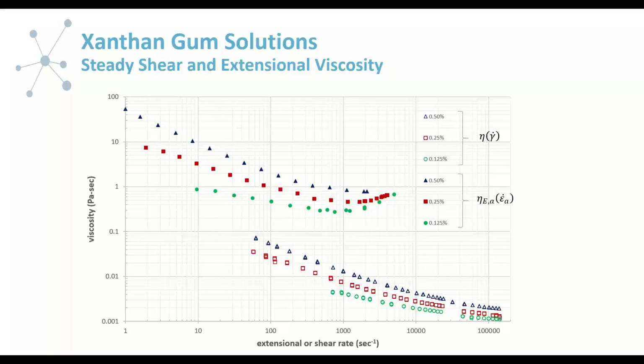And this is true even for Newtonian fluids, but it can be exaggerated for complex fluids, such as this high molecular weight polymer solution. The other thing to notice is that although we see thinning, or reduction in the viscosity as a function of rate, in the extensional case what looks like it might be extensional thickening, or an increase in the extensional viscosity, is absent down here under the steady shear conditions. And this is something we're going to look at in more detail next time.